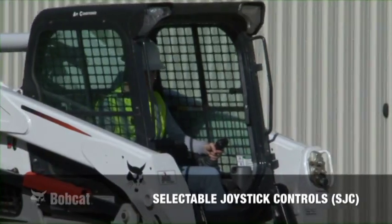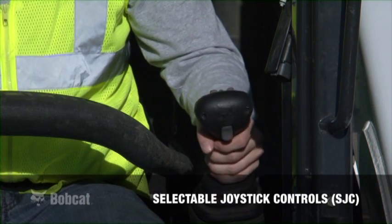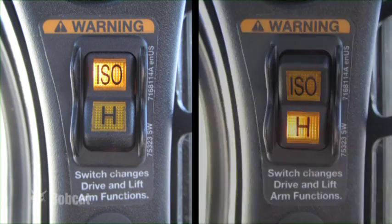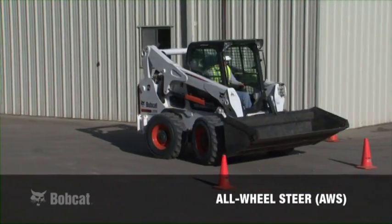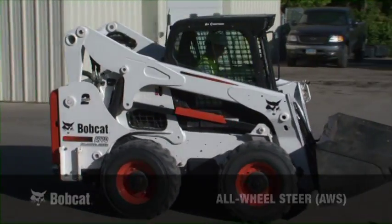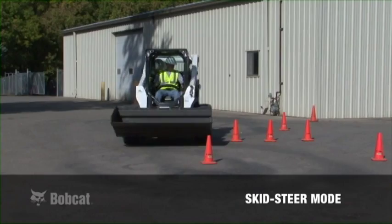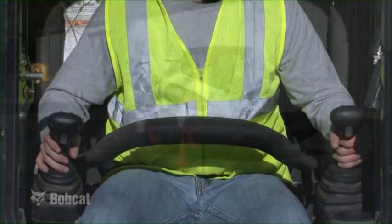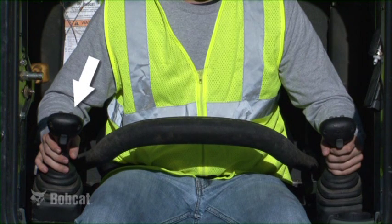Loaders equipped with selectable joystick controls, or SJC, provide joysticks to control drive, steering, lift and tilt functions. 2 control patterns are available, ISO and H. The Bobcat all-wheel steer, or AWS loaders, also provide joysticks to control drive, steering, lift, and tilt functions. The operator can select between 2 different steering modes, the all-wheel steer and the skid steer mode. Regardless of the steering mode selected, the left joystick controls drive and steering functions, while the right joystick controls lift and tilt functions.